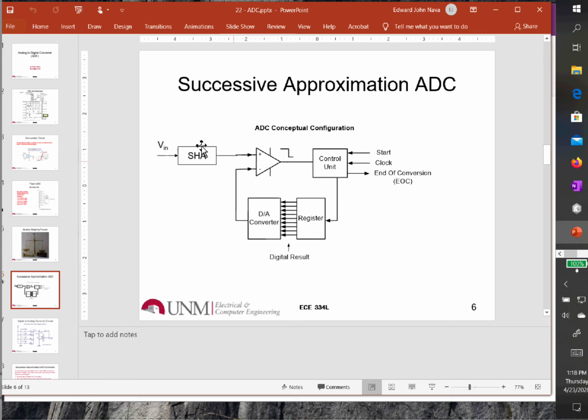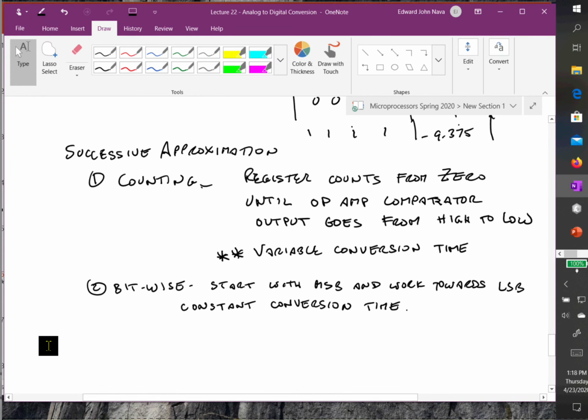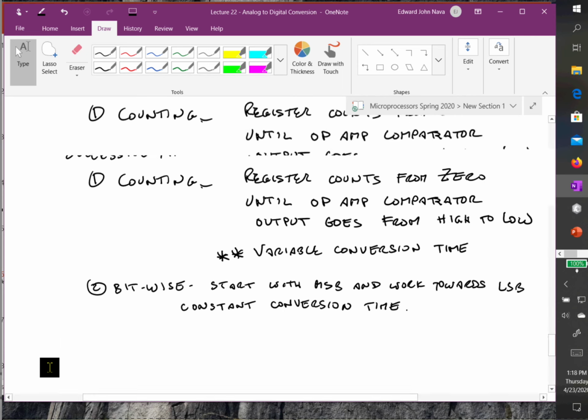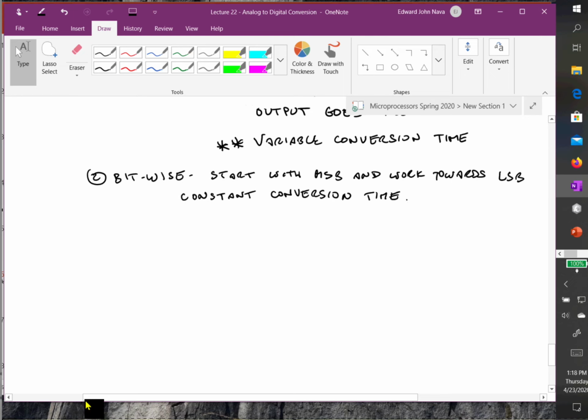Now the second question that comes in is this thing called an SHA. Imagine, have any of you ever tried to take a picture of a dog or a small child? You see they have a real nice pose, but as soon as they see you with the camera, they move. Well, we have the same thing when we're trying to sample signals. Real life signals change with time.